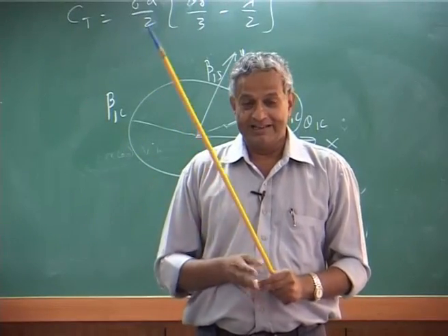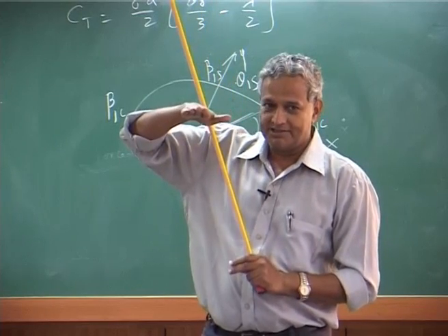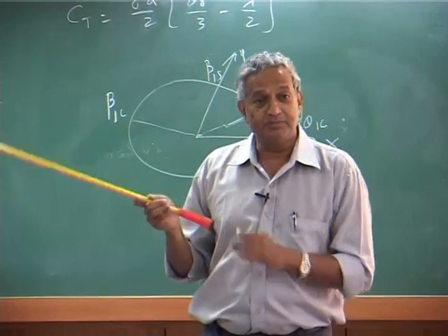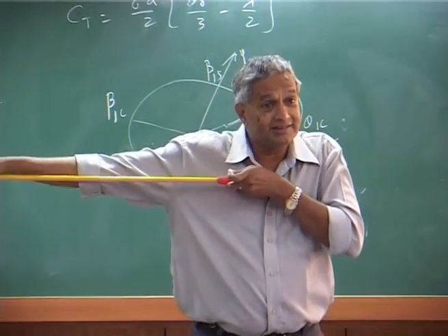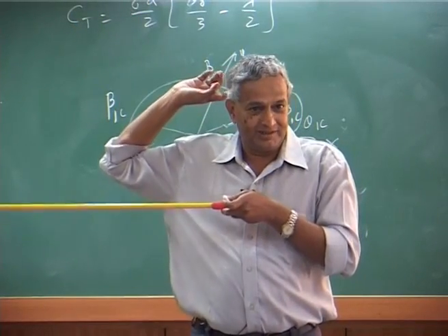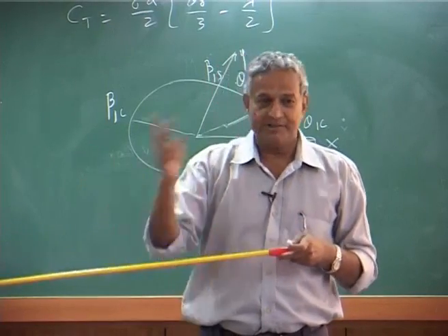Now, if the rotor disc is to tilt forward down, you must change the pitch angle when the blade is here, not at the 0. This is the key, important. There is a phase shift of 90.